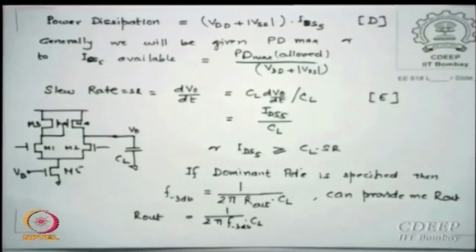So I must know that for a given temperature rise with the available thermal resistance of the path, I know how much delta P is possible, that is P possible. So power is limited by the heat sink and not anything else. Is that correct? If you can remove the heat, you can guess from this, your laptops or nowadays iPads or whatever Android based any other handheld system, they have been very low in power for a variety of reasons,